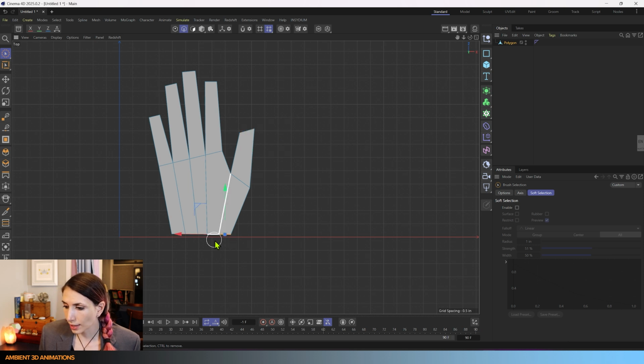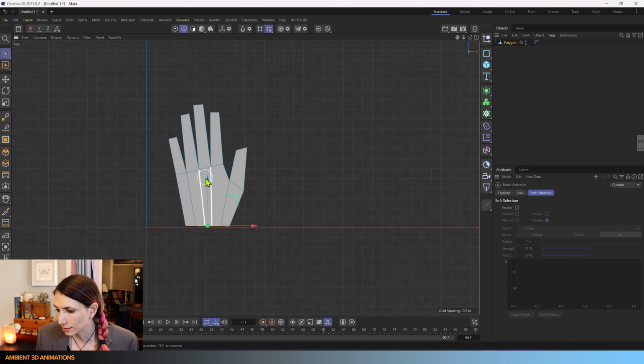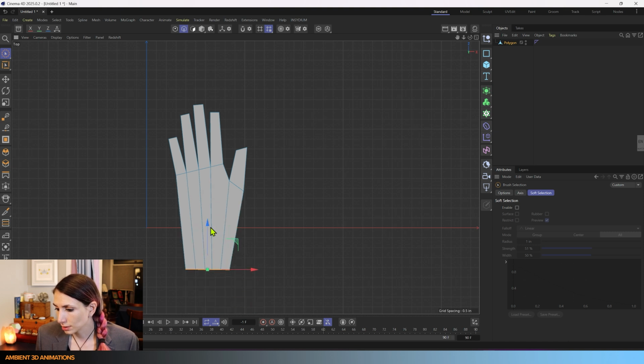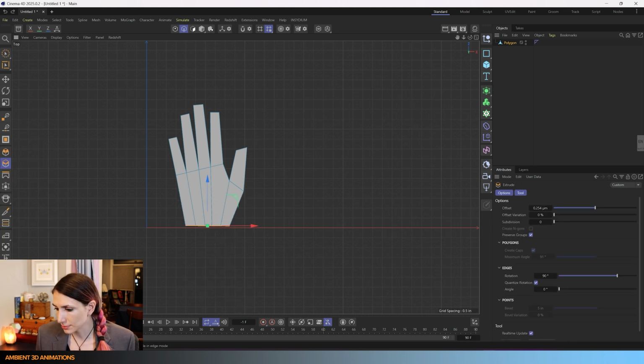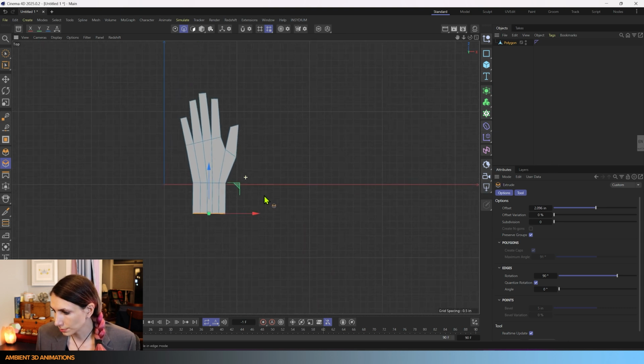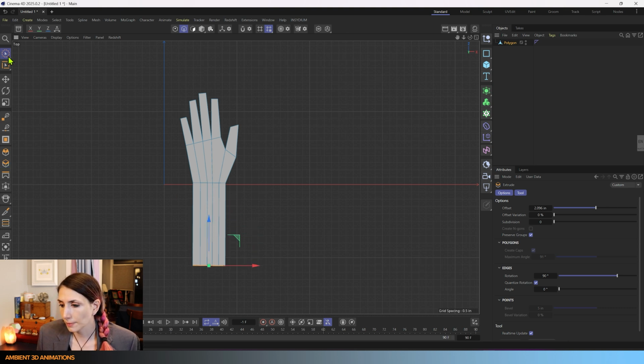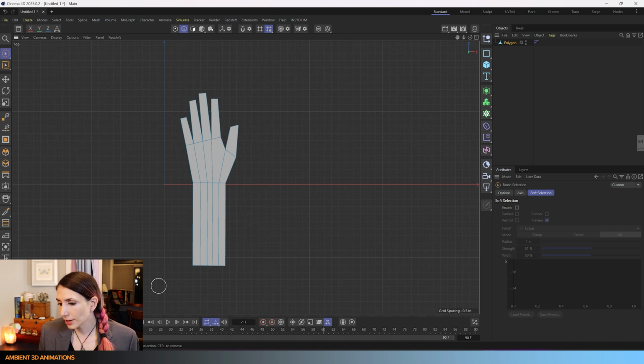And if we want to go ahead and make the wrist, I can go ahead and do that. So I'm selecting those and then I'm holding Control and dragging my mouse over those top edges so that I can extrude this on down. I'm holding Control, but I think I'll use MT in order to extrude this out instead. So that's extrude, the hotkey for extrude. And we have this very basic shape of a hand, which is great.